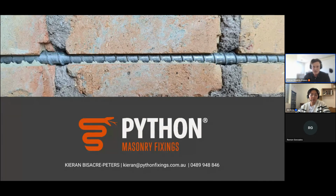Sometimes a statistical approach will be taken where, say, you implement 10% more anchors than what you need to account for those cases where you might hit a mortar joint, for example. Other options are sometimes site testing. An anchor site testing program will be run where you test anchors in the mortar joints or with close spaces to the edge of the bricks, just to give you a workable design capacity to use to account for those situations. All right, thank you.